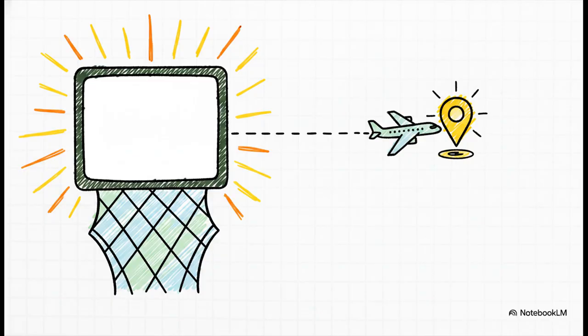But don't worry, the engineers built in a brilliant safety net. It's basically an automatic failsafe to illuminate the display when you need it most. The MAP display will automatically turn itself on when either the TO waypoint or the next waypoint, NX, is a designated missed approach waypoint. It knows you're getting close, so it forces the data to display.